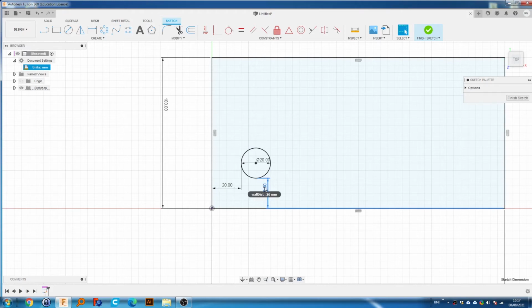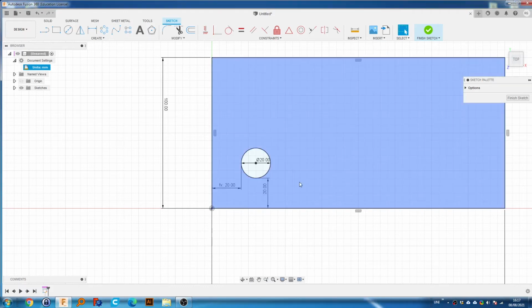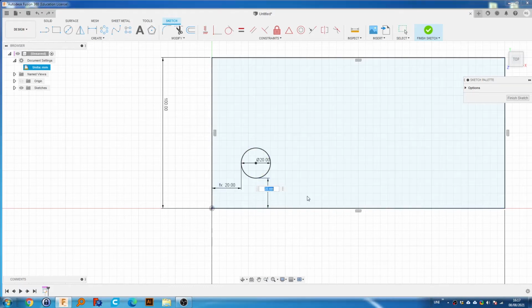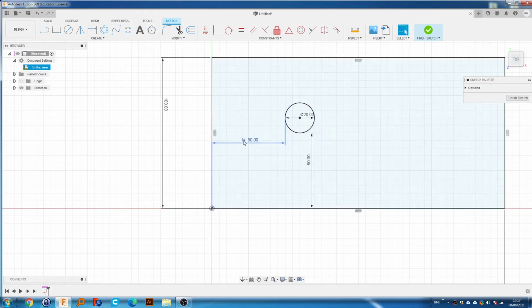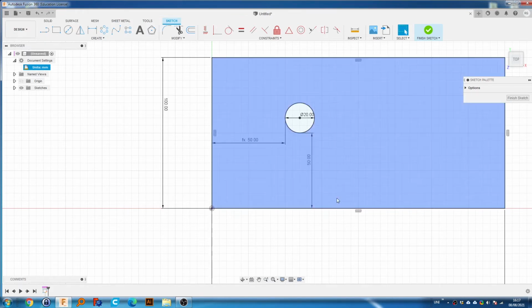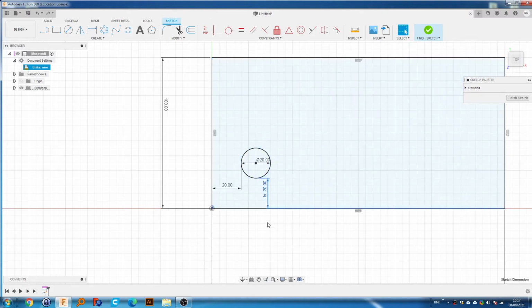Now, if we hover over that, it says wall dist. Now we can type in wall dist here, and you can see that it shows up here. So we can click on that, click enter, and now whatever we make this, let's try something a little smaller than that. Let's try 50. This updates to match that. Okay, so that's enough for user parameters, for example.